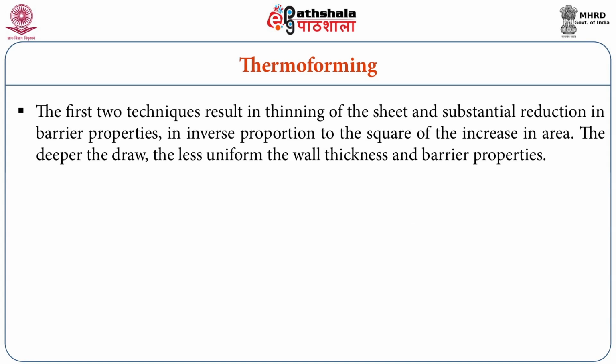female molds. The first two techniques result in thinning of the sheet and substantial reduction in barrier properties, in inverse proportion to the square of the increase in area. The deeper the draw, the less uniform the wall thickness and barrier properties.